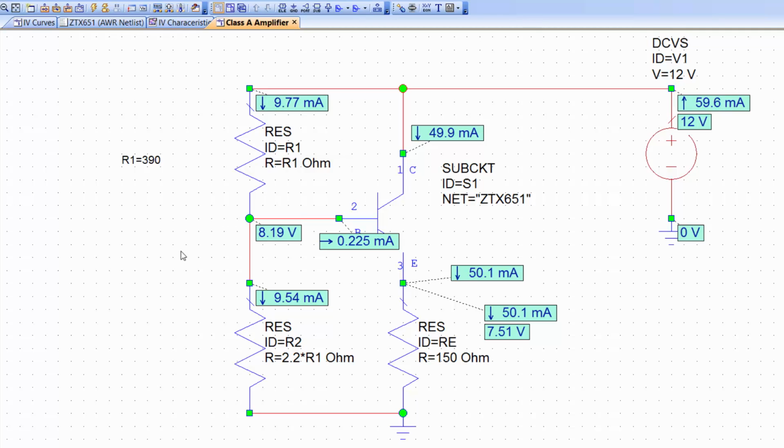Of course, if you think about it, the transistor is a current amplifier, so the current that you inject into the base then gets amplified and comes out of the emitter, amplified by a certain factor. So the more current goes into the base, the higher the current that would be going through the emitter and the collector. So if I increase the value of R2, as I've done here, then R2 will oppose more resistance to the current that comes from R1, and hence more current will flow into the base. Because more current flows into the base, due to the fact that this resistor is now higher, then you get a higher current coming out of the emitter and collector terminals.